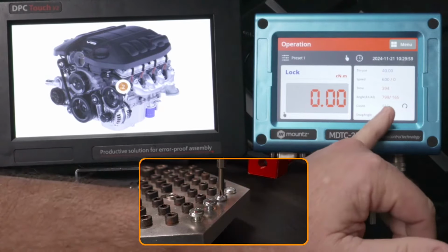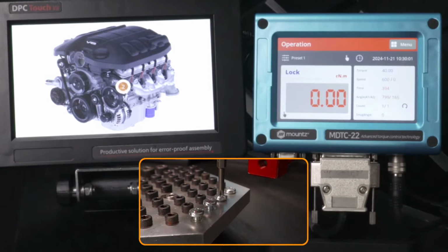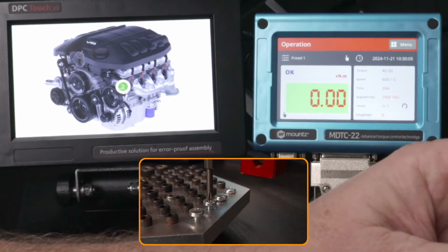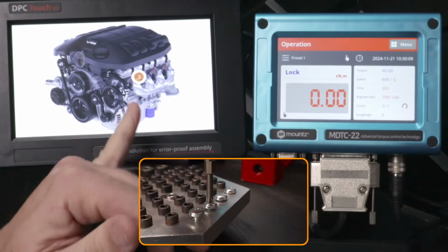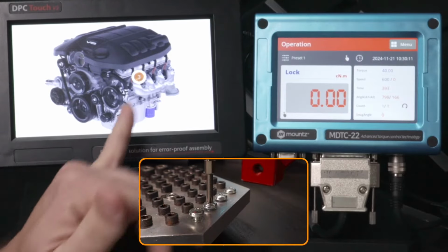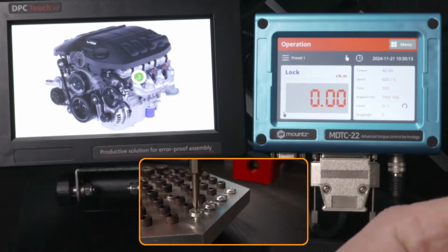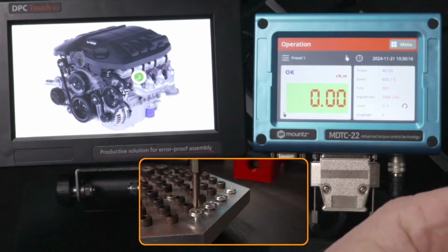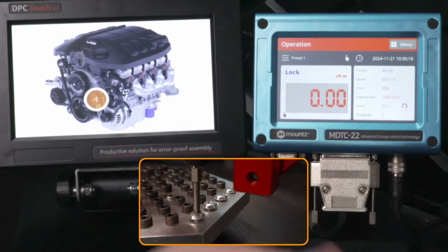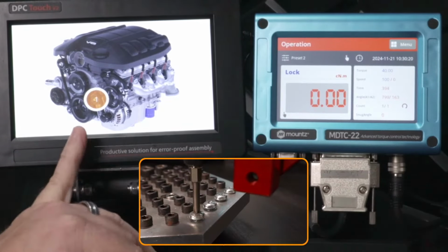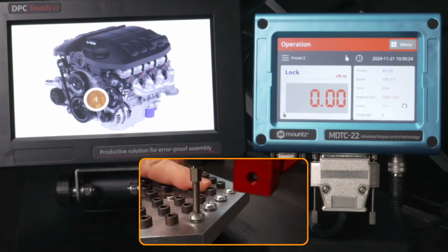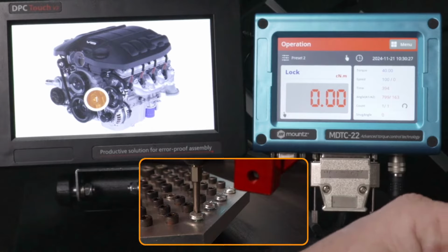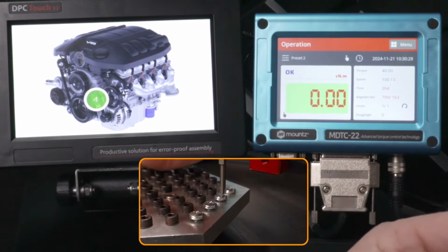You can see that we ran our 800 degrees of rotation, and we'll go ahead and move to the next step. Again, we're using preset 1. We got a good result. It is now indexed to the third fastening location. And now we have moved back to our first position on our fastener. And now this one is going to be different.